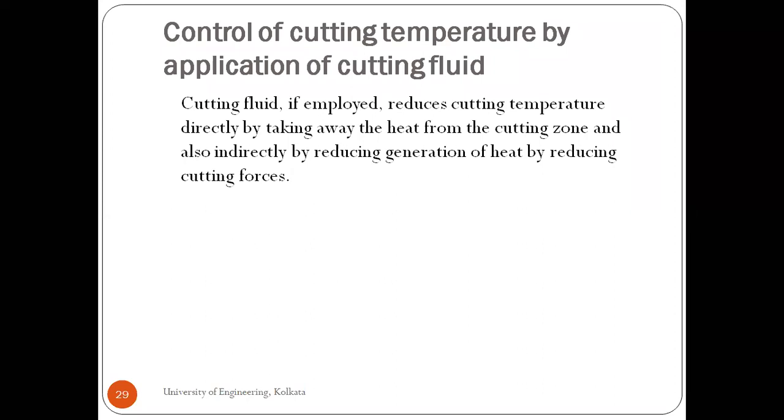Second, it reduces the friction, or it acts as a lubricant at the cutting zone. And third, it also takes away the chips along with the flow of the cutting fluid. So these are the three functions of the cutting fluid.